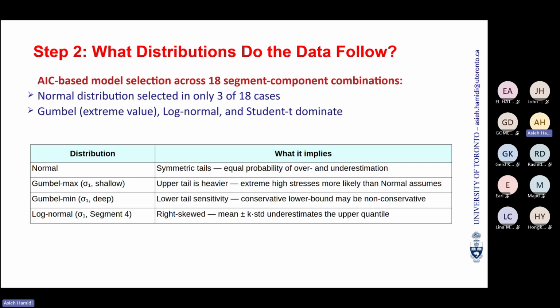We also have some negative values, which are valid, belonging to principal stress sigma 3. And we have some tails, which are the most important for a designer, because it is what we use for an optimal design, for a safer design.